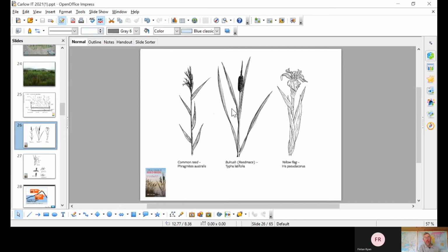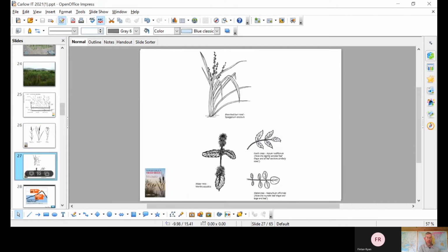Whereas in the soil-based wetland, it's actually the leaf litter at the top surface that provides the active site for bacteria to stick to. So we're just looking for material that will grow well, decay into the basin, and then provide that mat of leaf litter at the end of the season. So common reed, bulrush, yellow flag iris, and a number of others. Branched bur-reed is another common one that I'd use.